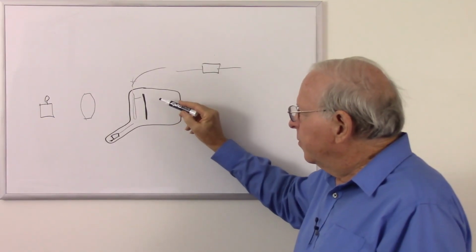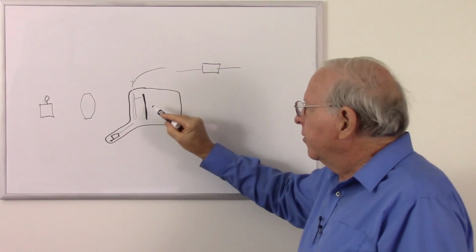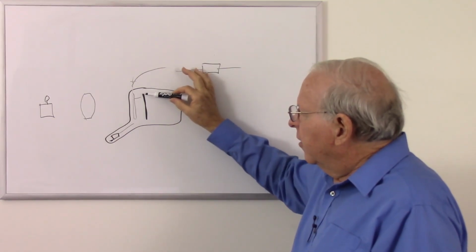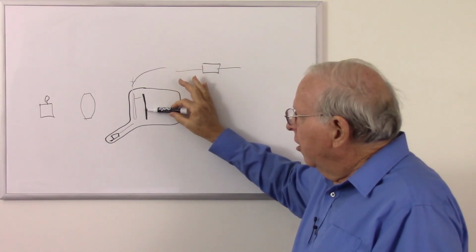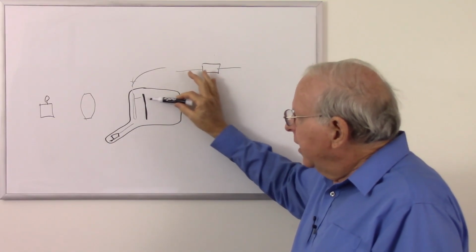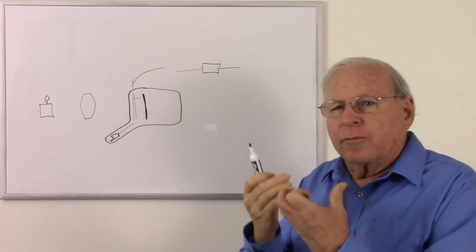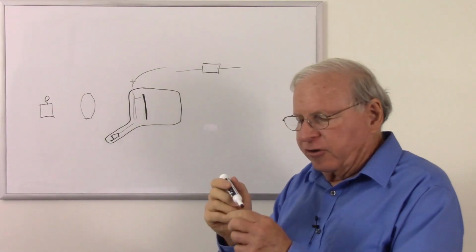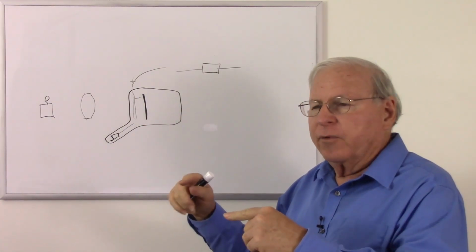And the iconoscope was later developed so that the electron gun was moved to the rear, and so it didn't have to be painted from the front. But the big advantage of the iconoscope was that it could store charge here, so that as the light hit the photosensitive pieces, they would store more and more charge, and so we weren't wasting that information, such as in the image dissector where we had the electrons coming back in real time.